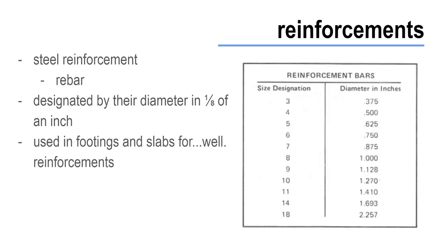Within your footing and your foundation wall as well, you'll typically see steel reinforcements, which are commonly just known as rebars. Rebars are measured based on their diameters in eighths of an inch. And so there's a little chart there that helps you, I guess, why can't I think of the word? Convert the rebar size number to how big it would be in reality.